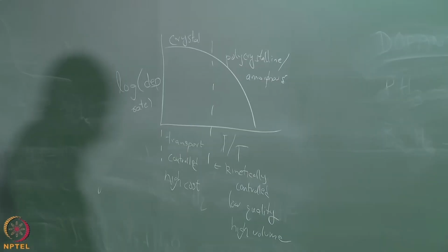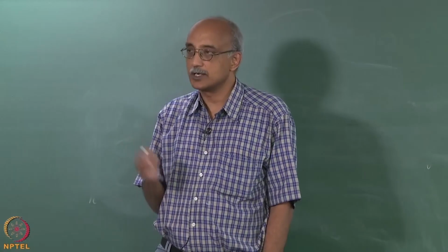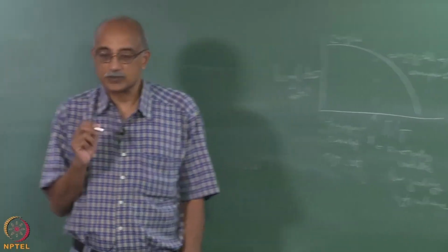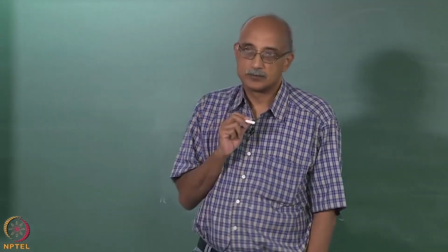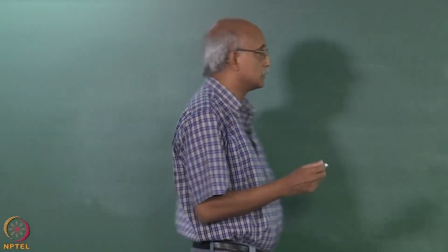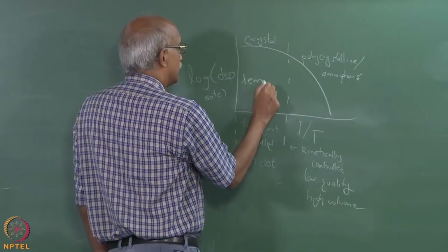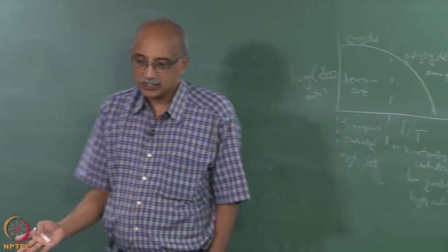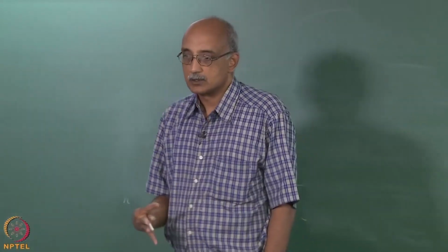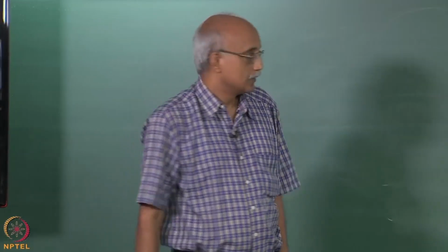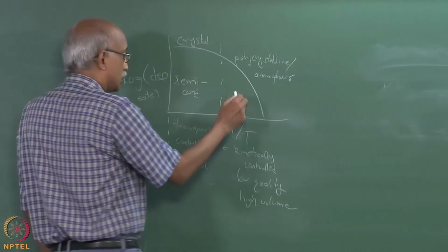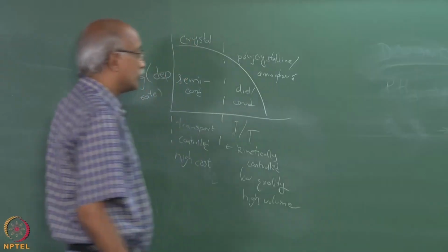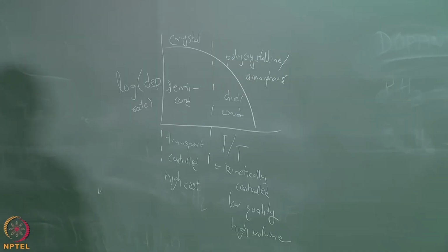How about semiconductors versus insulators versus metals? Where would you like to be? Again, for semiconductors, most of the time you are looking for a very crystalline structure because of the types of applications that are used in. So, semiconductor CVD is typically done in this regime, where temperature essentially does not have a significant influence on the deposition rate, whereas your dielectrics and conductors are more likely to be deposited on the right side of this curve.